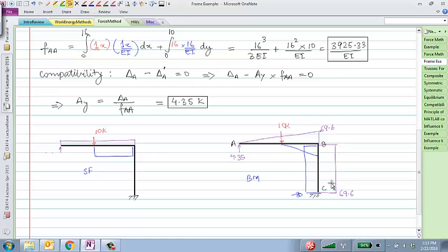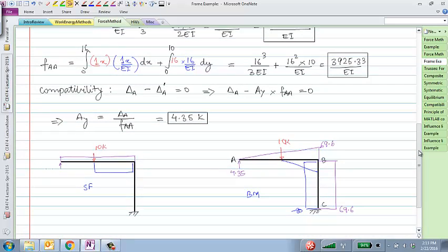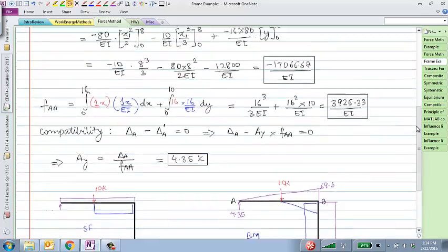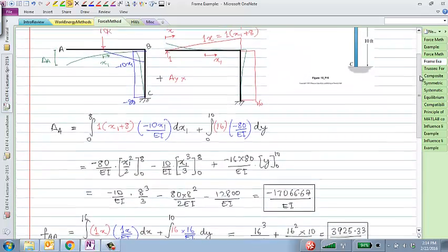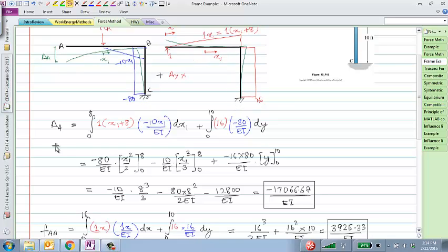Okay, so not terribly complicated, but the fact that we use the virtual work method and not any tables is not terribly more complicated either. If you are able to use the tables to calculate these flexibility coefficients, great. But not all problems are as simple as those tables. And even if they are not as simple as those tables, you can see right here, once you draw the bending moment diagrams, the displacements and the flexibilities are practically one-line integrals.